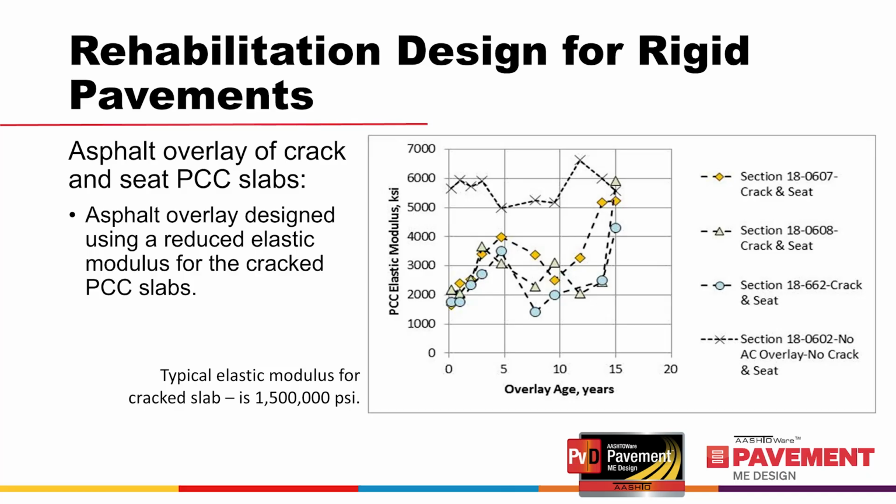For design input compatibility, the asphalt overlay of an intact PCC slab is the focus. The modulus of elasticity back-calculated from the FWD deflections measured on the slab interior represent the elastic modulus many years after original construction, while the PCC modulus of rupture is usually unavailable. So, the inputs to be used in the PMED software are the 28 days strength and modulus values. They must be compatible to get an adequate estimate of the fatigue damage.